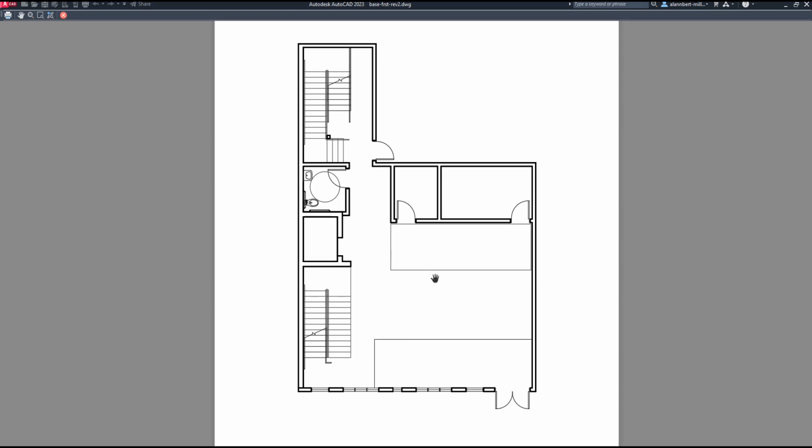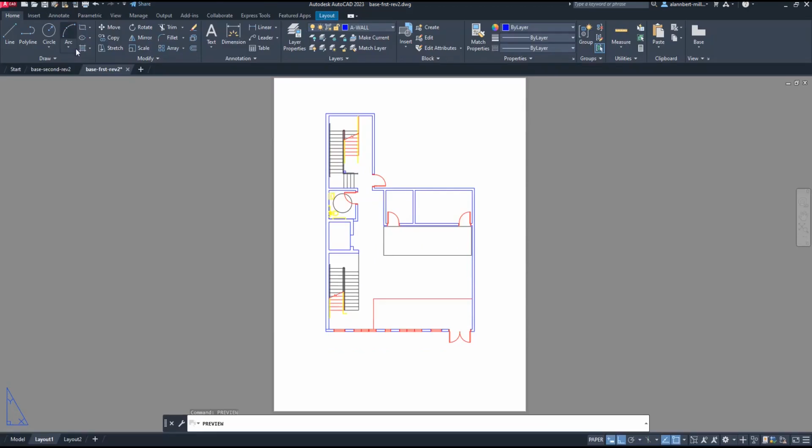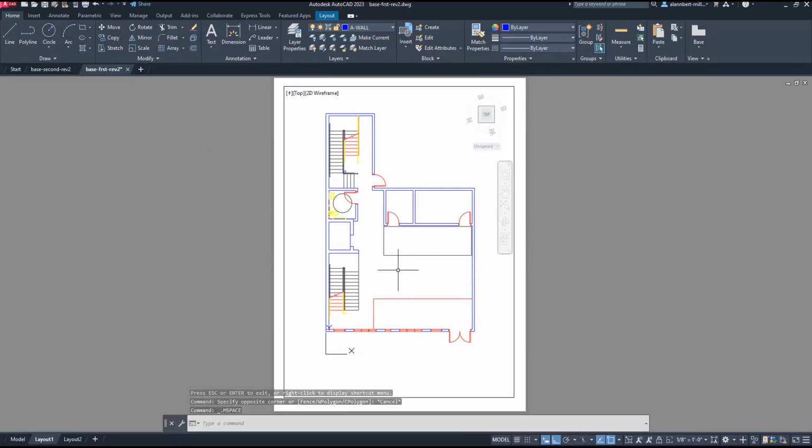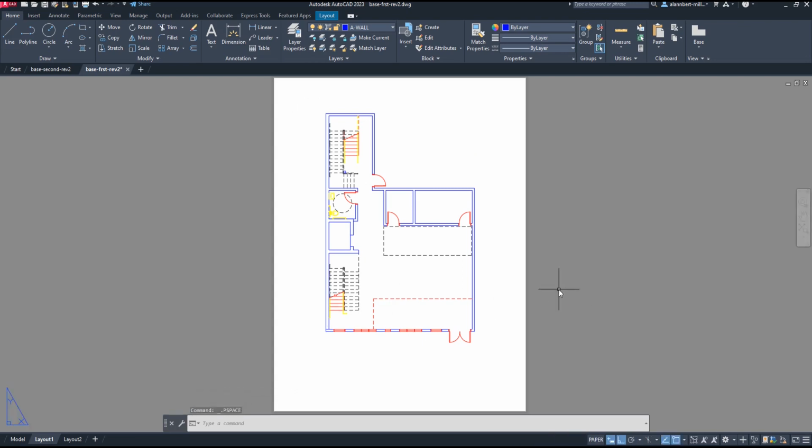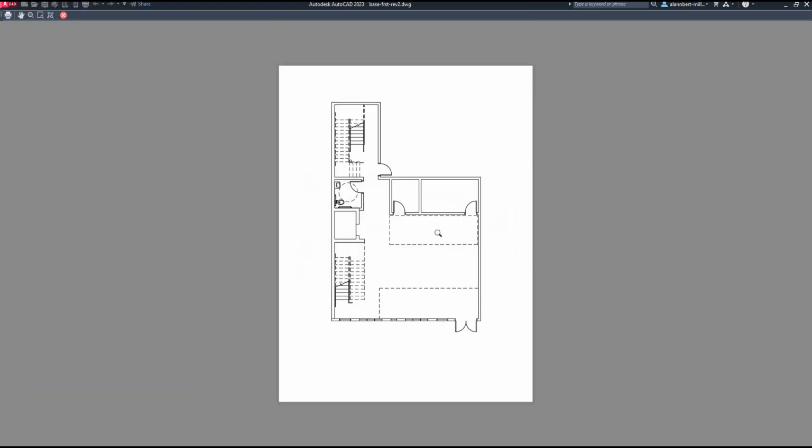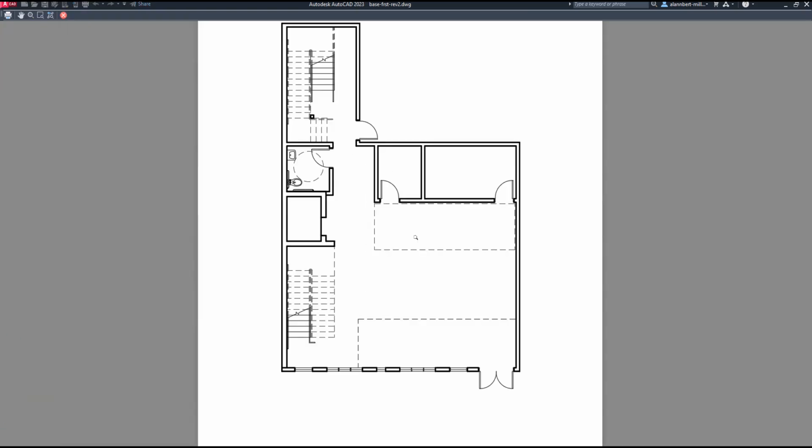Okay, so cancel the preview, press escape or close this. Double click here, type in LT scale, and the LT scale is 24. Let's bring it back to 1. Press enter. There you go. It's too long for me, so I'll do another LT scale, and I'll adjust it to half of it, 0.5. If you like it, you leave it that way. Let's do another preview. Oh, double click outside first, and then let's do a preview. And there you go.